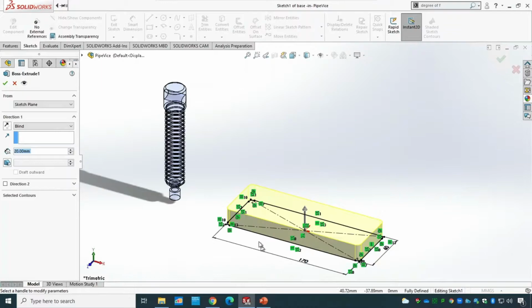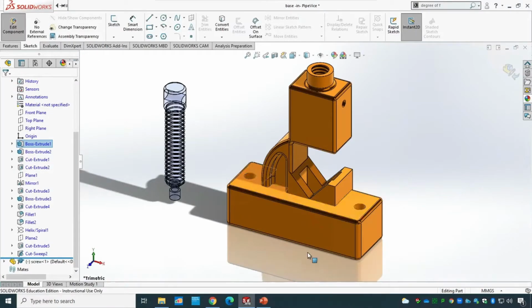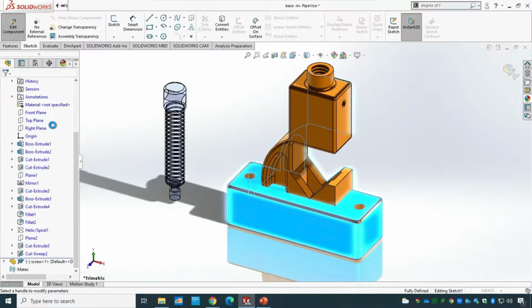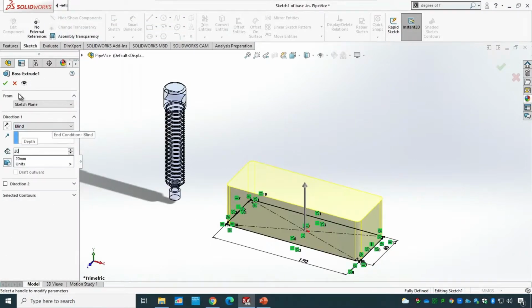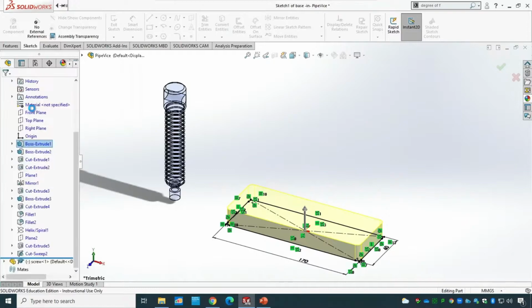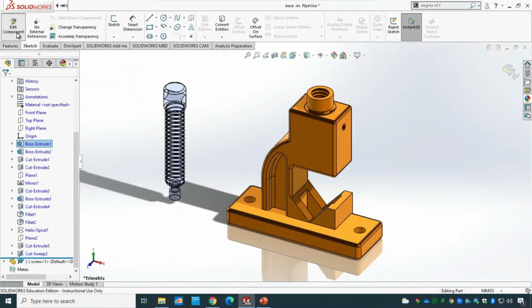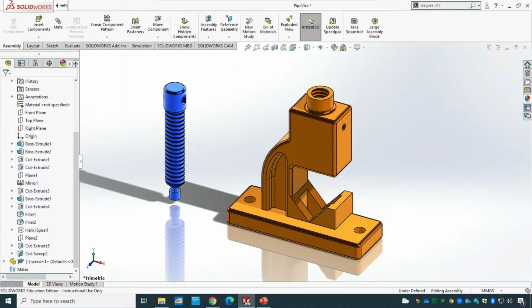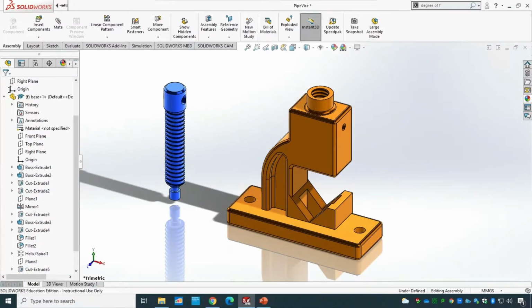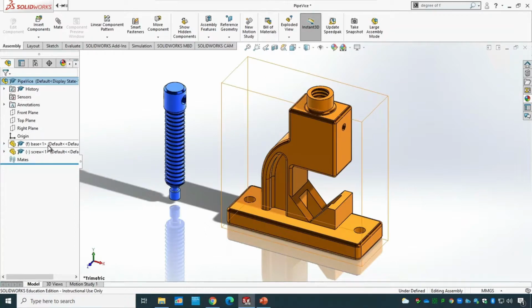And you can see, for instance, that extrude from 20, let's change it to 50, and I'm going to bring it back to 20 again, and you can see the full model is going to be updated. So I can also edit components while I'm at the assembly stage. So let me go back and change that one to 20. Click OK. And once you're happy with that modification, you can click on that edit components, and you will come back again to the assembly level. As easy as that. And that was the first component that we're working on, called base.